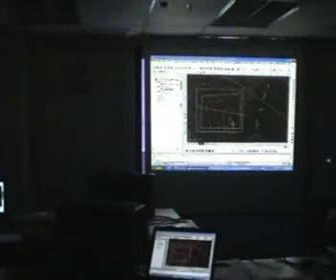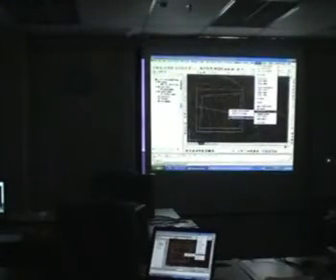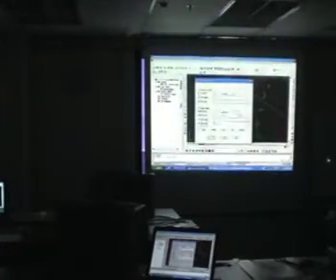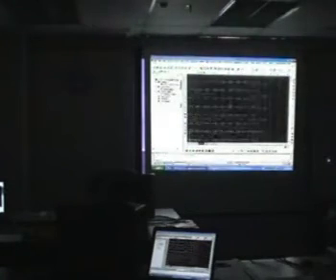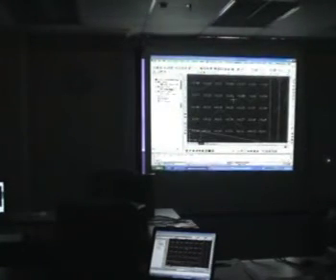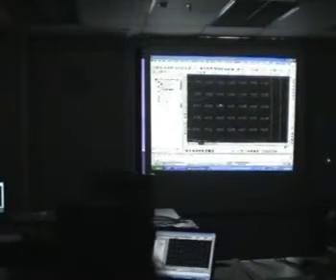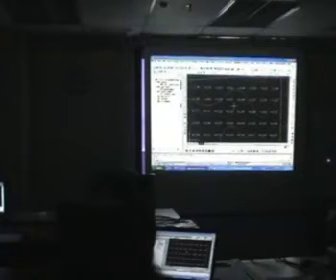If, let's say, you need to generate any drawings based on those volume calculations, for example, you want to have grid volume ticks, you just go to grid volumes. There's an option here, grid volume ticks. You click OK and you specify what the interval is between each tick. I'm going to use an interval of 10. Click OK, and I'm going to zoom in so you can see the values. This is for when you print a drawing like this for your contractor, so at least they know how you're going to level out the existing area. Plus indicates, of course, fill, and minus indicates the cut.